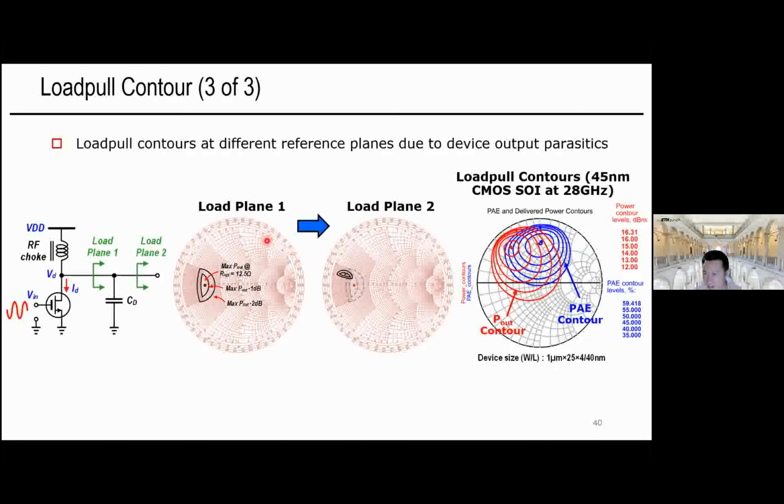Now, for other types of PAs, for example Doherty PAs, the main PA should operate at 6 dB power backoff by itself, before any active load modulation is turned on. In that case, you should actually use the backed off input drive so that we can find the optimal gamma L. So in those backoff cases, it depends on the applications. But for the basic practice, class A PAs, as a starting point, you can certainly use the continuous wave at around the 1 dB compression point input drive to find your starting point of the gamma L, and then start your optimization from there.